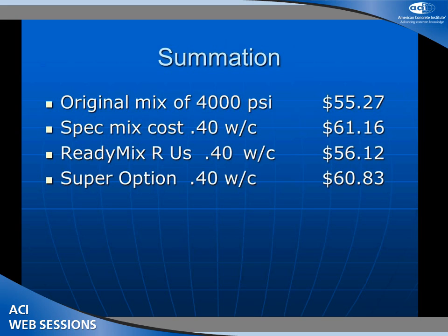So we went through the scenario of the 0.40 water-cement ratio versus a strength mix, and I explained to him what it takes to get concrete out of the truck, and he was kind of amazed. And then he one-upped me with that 510 scenario. He actually told me one of my competitors was using 470 pounds of pure portland cement and got the water down to 22 gallons a yard. If anybody's in the ready-mix industry, there's no way you're going to make concrete with 22 gallons of water. That was an improved mix, and they used it.